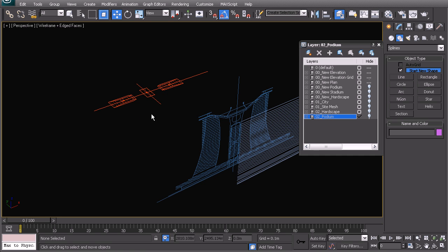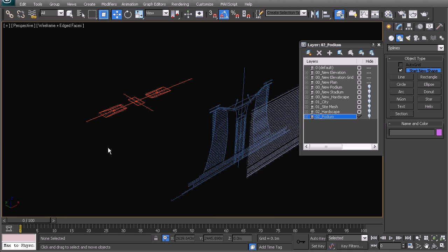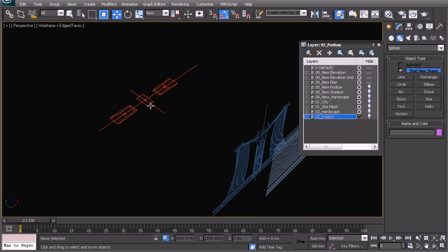The reason why I want to do that is I want to keep a flexibility in my model where I have in my history on the side here the original pure form from which that building is derived, just in case the client comes to us and says, oh look, we've run out of budget, we now need to make the building perfectly vertical and we want you to remodel the whole thing, and then you have to go back and restart the whole process. So instead, if you have that pure geometry, you always have something to fall back on in case the client takes a step back in his decisions. So that is something that I think has a lot of power to it, so we will use that method as we build this.